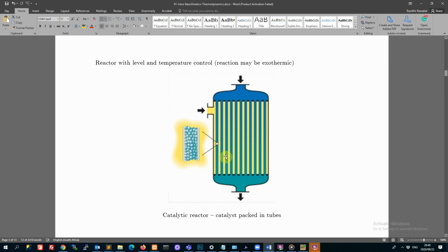We want to know how fast things are flowing through the system, how the molecules are diffusing through the particles, and how they are contacting us. So what's the rate? The rate is varying across the reactor. The rate is not one thing. You can't say, I measured the rate here and it was 50 moles per second per cubic meter, and that's the rate in the whole reactor. The rate might be changing a lot down the tube. It might be 50 up here, but because the components get converted, by the time we're looking down here, we might have even a zero reaction rate.